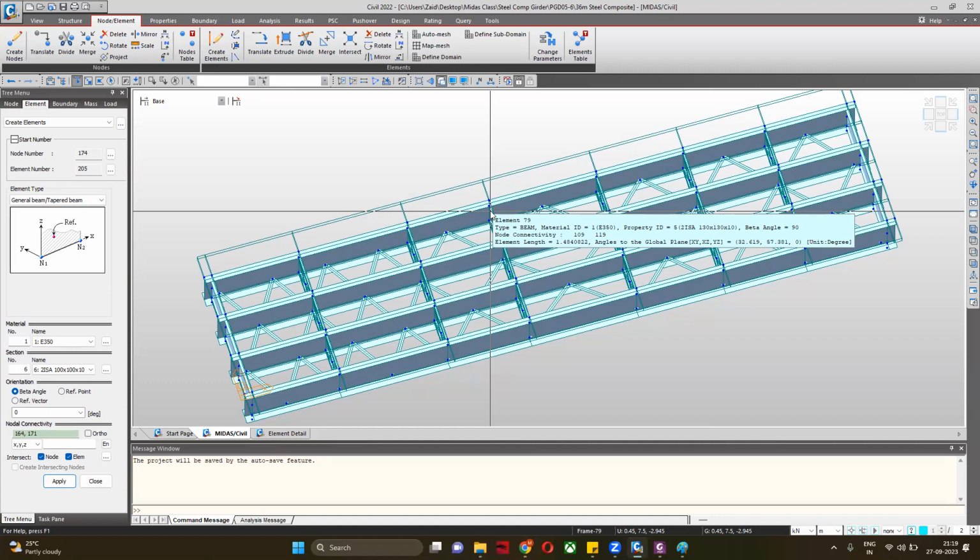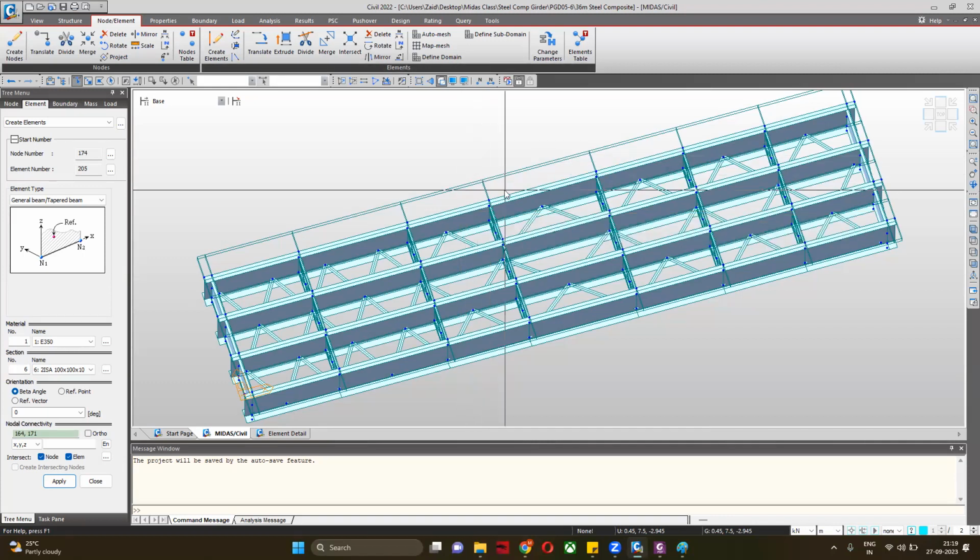In concrete, everything is moment connected. We have some secondary or primary beams, but everything is connected through concrete. Nothing is freely or shear connected. That's why steel is very good, so we can differentiate our joints, or play with the joints according to our requirements.